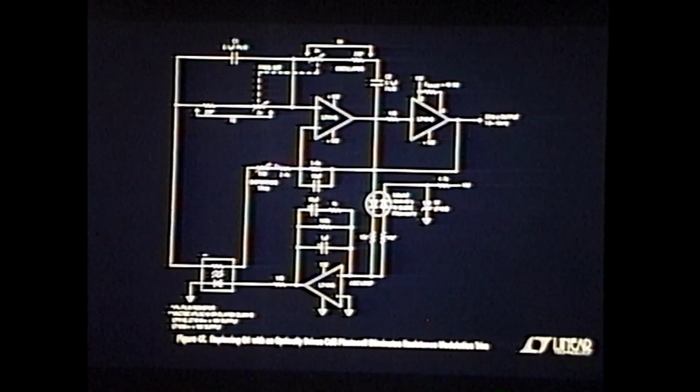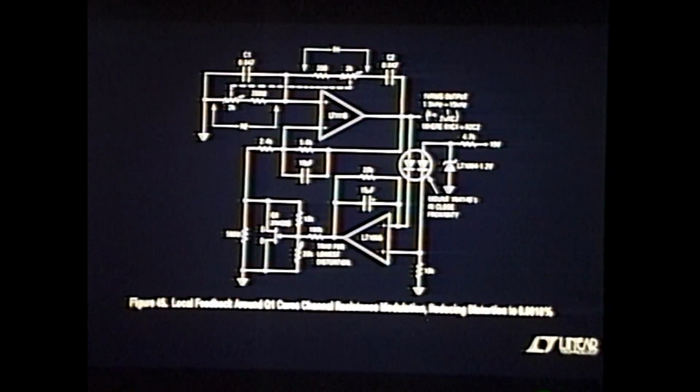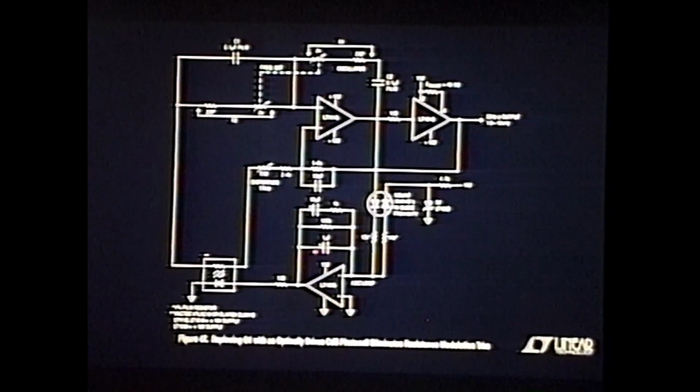I come around here. Here's my resistor negative feedback network. Same AGC network with one change. You notice my frequency compensation in here is a little different. Before, I had what I call grunt compensation. You've just got a huge time constant in the loop. Here I'm getting a little fancier. Big time constant in the loop, but I've got a little bit of lead there. I'm trying to get fast settling here. This is the real meat of the change of the circuit.